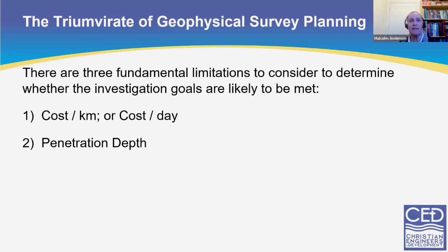Then the next one is the penetration depth. Every method has a different penetration depth, and some are unable to get to the depths that boreholes typically extend down to, but still cover wells and shallow boreholes. So penetration depth is a key factor. If your goal is to put in dug wells, then most methods will work. If your goal is to put in a deep borehole, then a fair number won't.